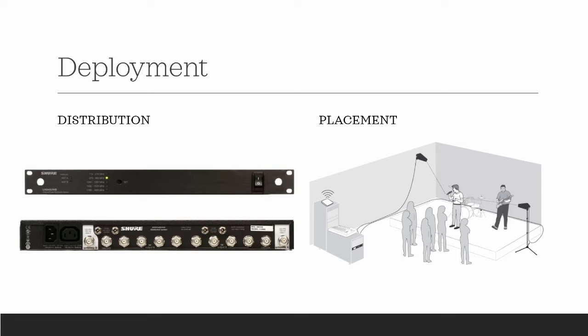One, it's ugly. Two, we set ourselves up for failure, because all of those antennas can get bumped into. Now they can become loose. Why is this single channel not working? In addition, we create RF problems for ourselves when we have a bunch of antennas in close proximity. When we have transmit and receiver antennas on top of each other, we create more intermodulation effects. We really just want to avoid that if we can.